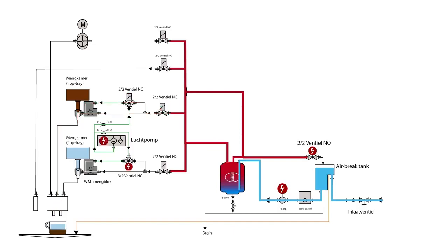The air pump and the three-way valve at the milk side switches on. This forces air through the tubes at the milk side. The air removes any water from the air channel and tubes to the mixing chamber.